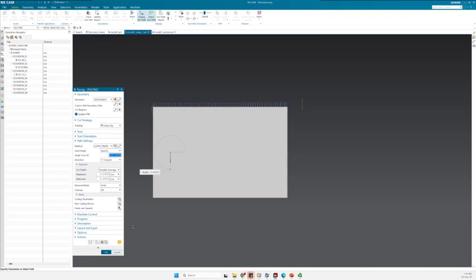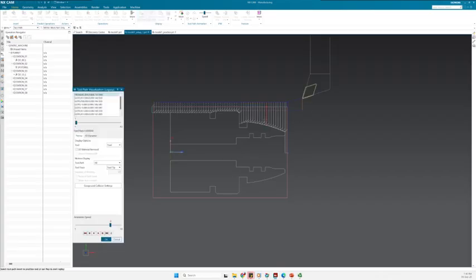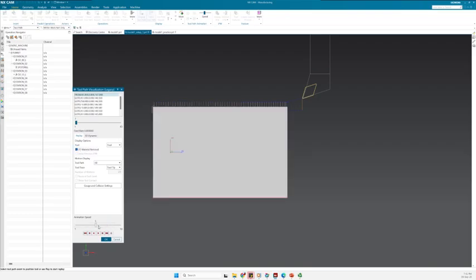But maybe this view is not very clear. So we go to the verify mode, and then I can see the toolpath. Pay attention, and you can see that the tool starts from this point. It goes and engages with the part, and then after that it's finished. It is this tool, this line, and then first comes axially out of the component and then radially up. So this is the first point and confirmation of the point that we have defined in the previous video.